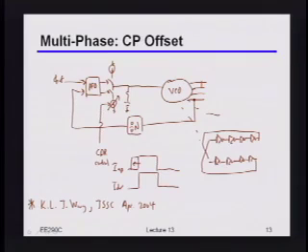When you have this, if you look at the CDR, do you also introduce another integration? Okay, so it's a good question. The question was, if I really do this, then it looks like my CDR updates are going through the PLL loop, right? So are you introducing an additional integration onto the CDR? Or is the bandwidth too high?